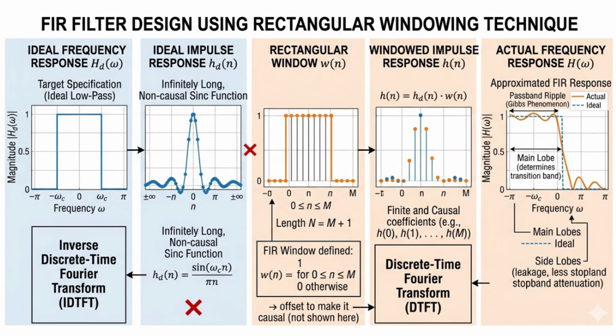Okay, so here now we will see FIR filter design using the rectangular window technique. So this is the rectangular window technique, all right? So for each of the impulse response, you can have the multiple of sinc functions, and if you add, then finally you will get this type of frequency response.